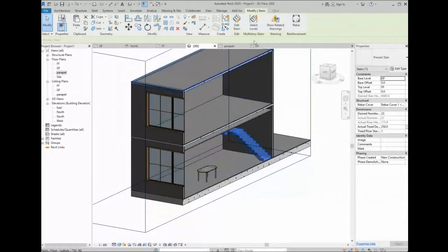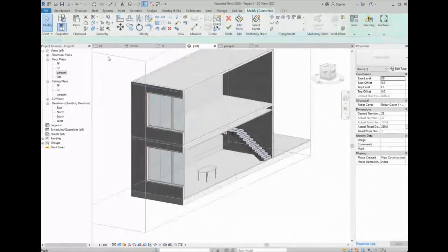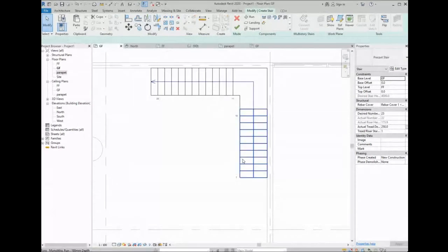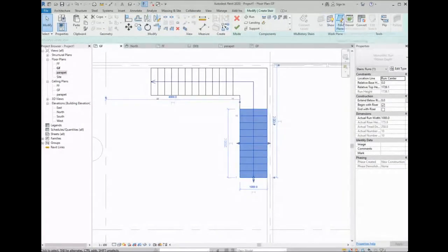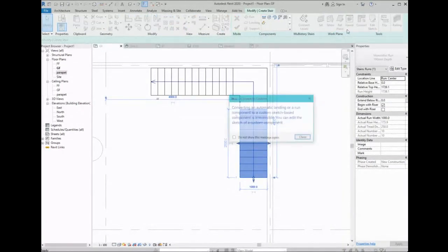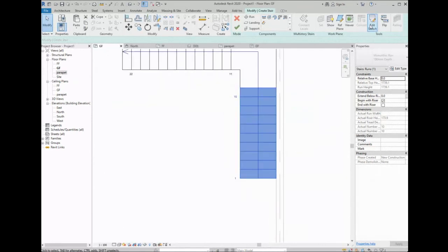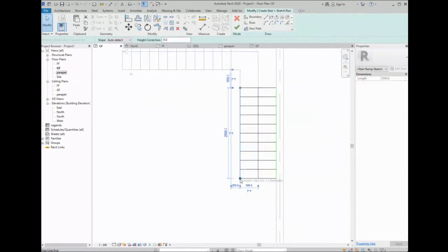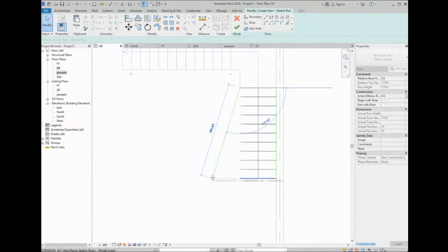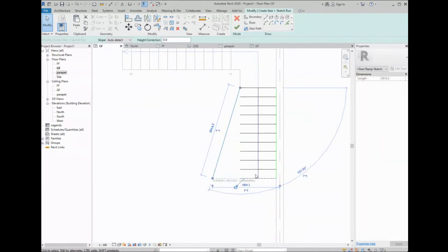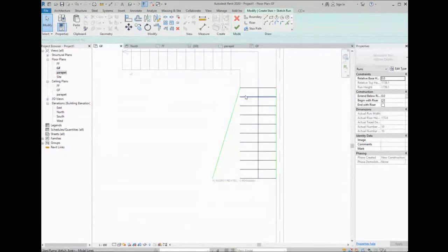So if I want to edit the stairs, again, we said we'll go to edit stair. Let me just go to the ground floor. Select, for example, this one, and then I will go to convert to sketch, close, and let's say edit sketch. Let's say I want to bring this one, this. Okay, now I have to connect all these lines to this one. I cannot keep them this way.